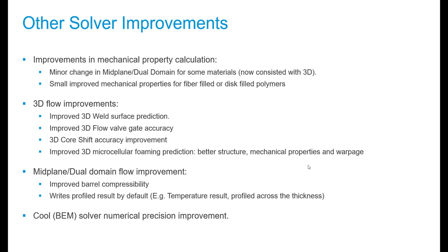That has as a consequence, though, that the amount of data we're producing now on a midplane and dual domain flow analysis is going to be significantly higher, because now we actually capture a lot of detailed data through the thickness at every time step. So there's a lot of data we're creating there, but you're going to have much better insights and be able to diagnose things a lot better.